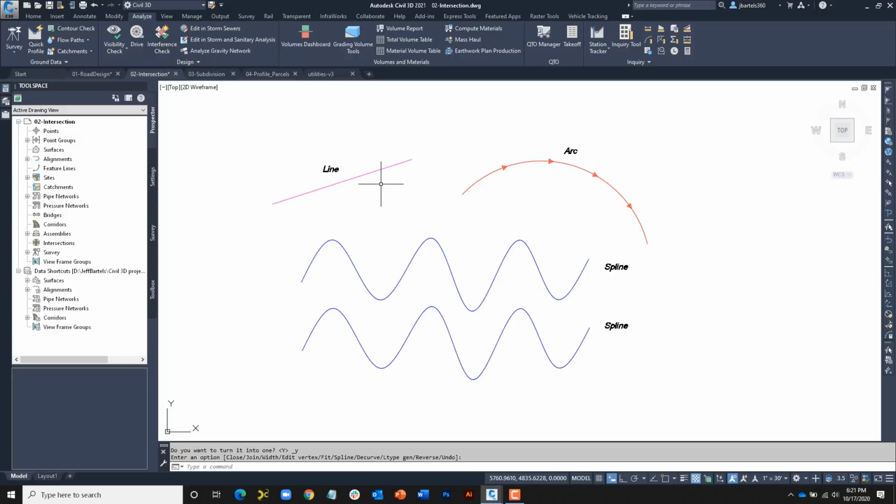Once again, you'd think that we'd go launch the pedit command. We don't have to. Just for a second, think about how we edit text in the AutoCAD platform. We double-click on it. We can edit polylines the same way. I'm just going to double-click, and it brings up the properties of the pedit command here at my cursor and down at the bottom of the screen. Let's choose width, and I will set this to 2 and press Enter. I'll press Escape when finished.